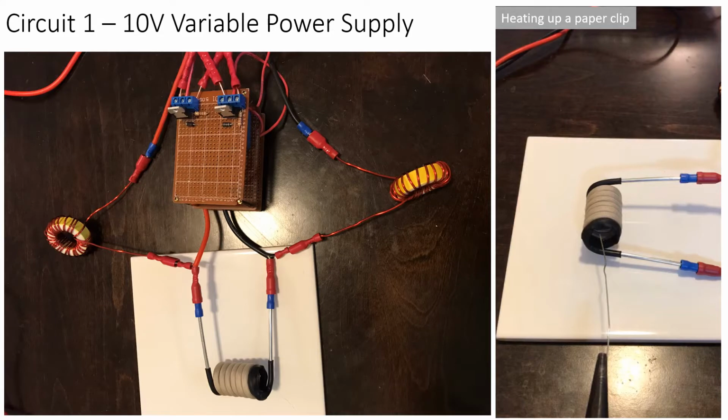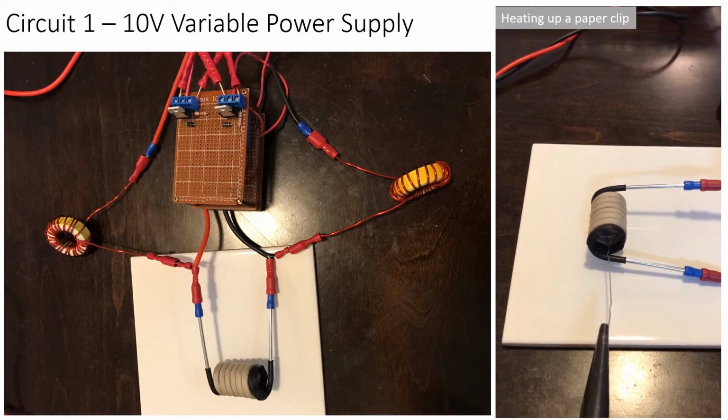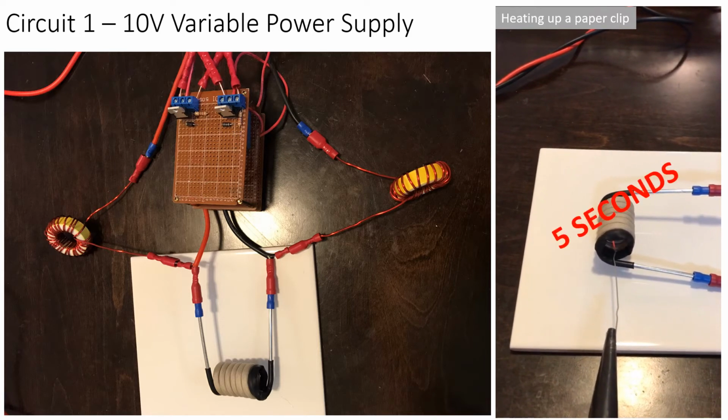My first experiment was using circuit 1 to heat up an unfolded paperclip with a thickness of 0.8 millimeters. For all of these demos, I measured the time it took for the object to get red hot to have a consistent basis of comparison. When the circuit was connected without any object in the coil, the variable power supply was set to 10 volts and had a 2.8 amp current draw. When the paperclip was inserted, the current draw increased to 3.9 amps. The paperclip took 5 seconds to heat to a red-hot glow.